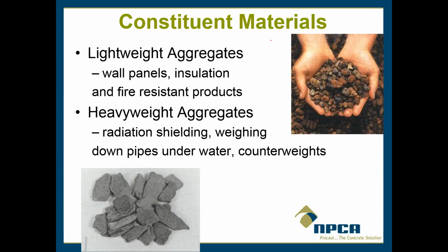Heavyweight aggregates, on the other hand, work really well in radiation shielding, and Claude also shared an example of counterweights. They're like in a washer to keep it from, sometimes you'll hear it banging around, something's not quite right. So anyway, heavyweight aggregates can be used for making concrete that needs to be very dense and heavier.